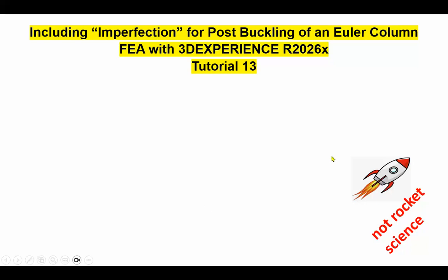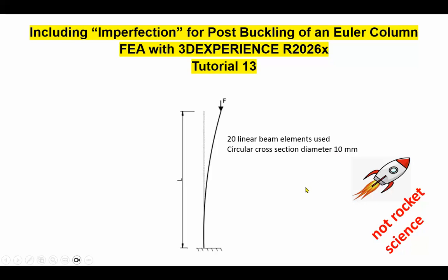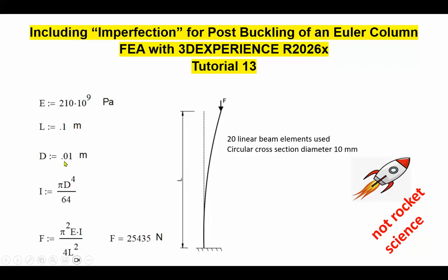Okay. So here's the classical Euler buckling problem, and from a second year engineering course in mechanics of materials, you can find these formulas, and the buckling value, the linear buckling value, is actually obtained by that formula, which is called the Euler buckling formula. Now, it's about 25,000 Newton based on the data that I have.